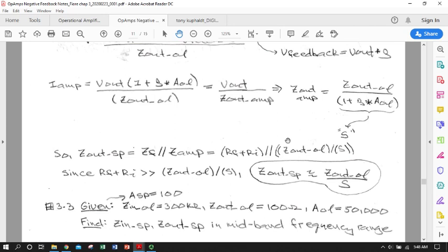We're going to take that small number and make it even smaller, because we're dividing by our sacrifice factor, which is always more than 1 and quite often considerably more than 1. So this path is very, very, very small compared to this path. So when we've got a parallel network and you've got one path that's the quickest, easiest path to ground, most of the current tends to follow it.